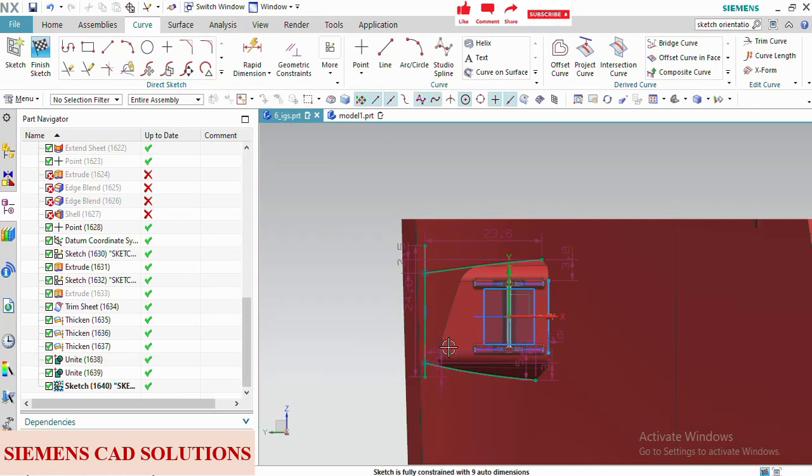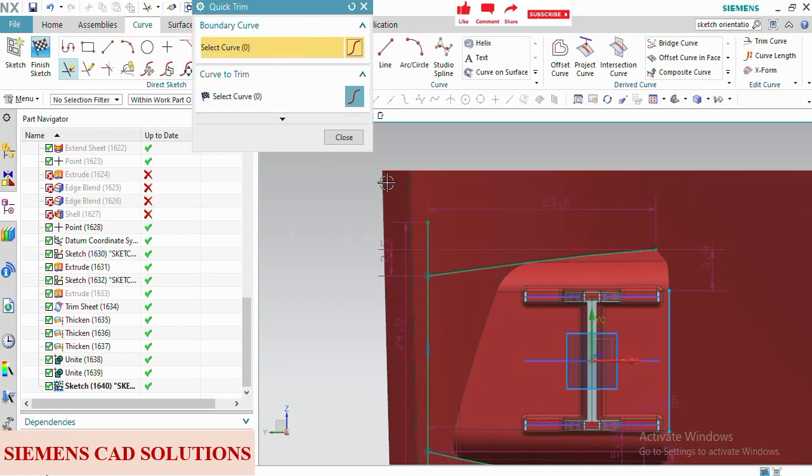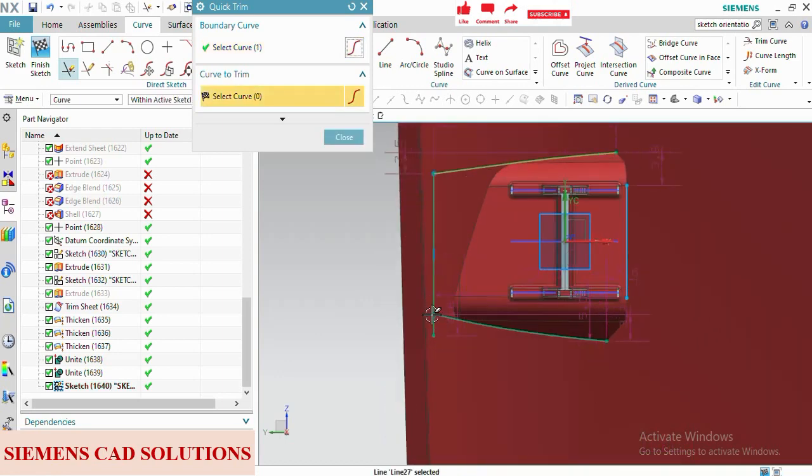If you are taking the inner edge of the profile, then you need to add some material. Whenever you are going to create a plastic part parametric, all the features will have draft.